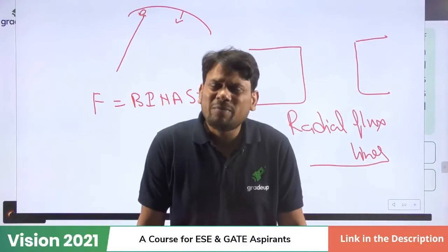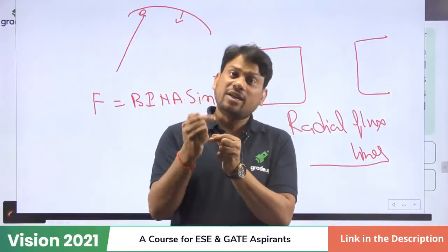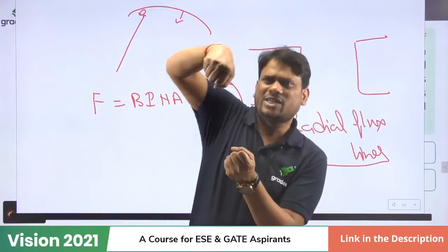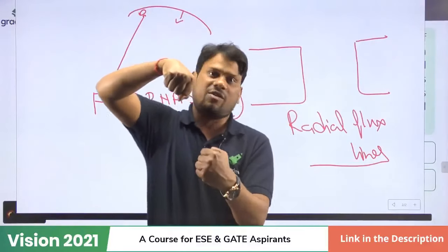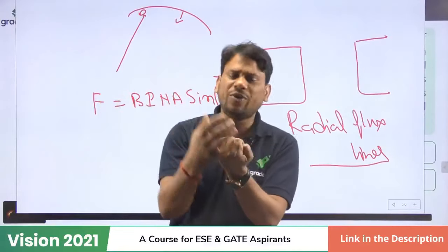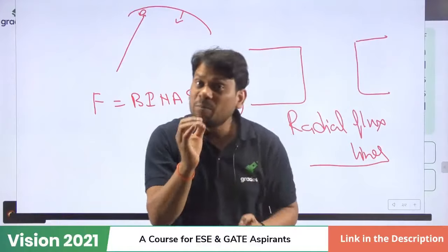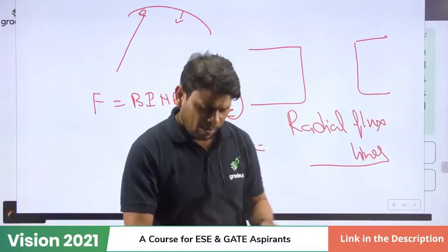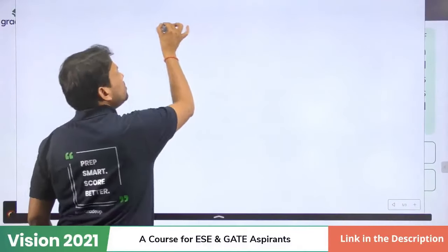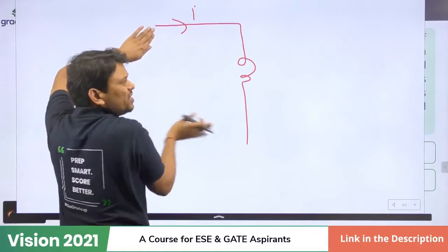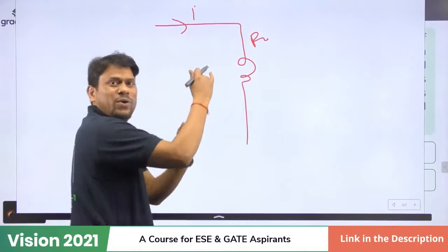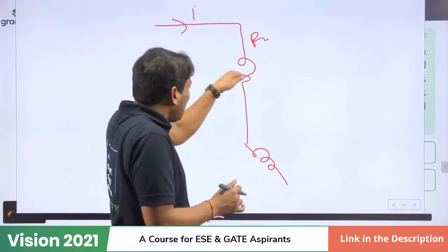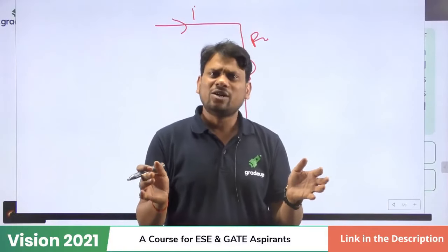Now listen to me carefully again, everyone. My question is, in PMMC we have one spring, and that spring provides the steady state deflection point. Suppose we have one rope and we apply some force to the rope in any direction. Then the rope will also apply a force against our force. That opposing force we can provide by a spring, but the main force we have to provide. The same thing we use in PMMC. When our coil passes current, it feels some force, so the coil starts to move. Then we require one spring, and that spring applies an opposite and equal force in steady state to our moving coil.